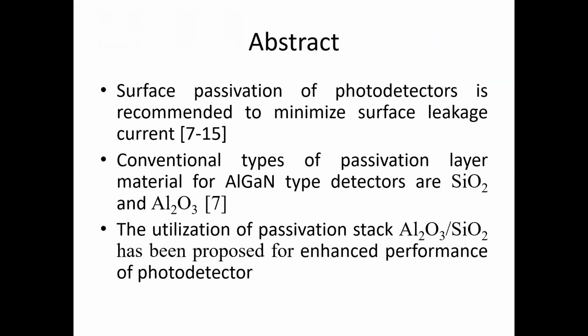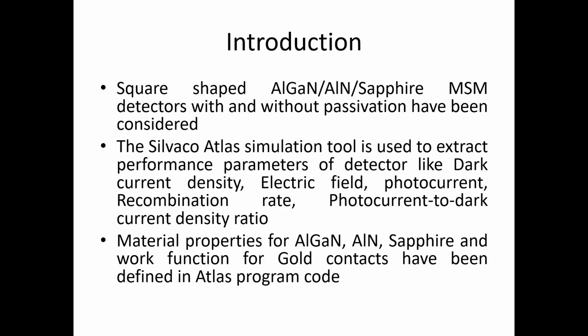That's why we have proposed the idea of using a surface passivation stack of an Al2O3/SiO2 based passivation layer stack for the enhanced performance of the photodetector. For this, we have selected the MSM detector.